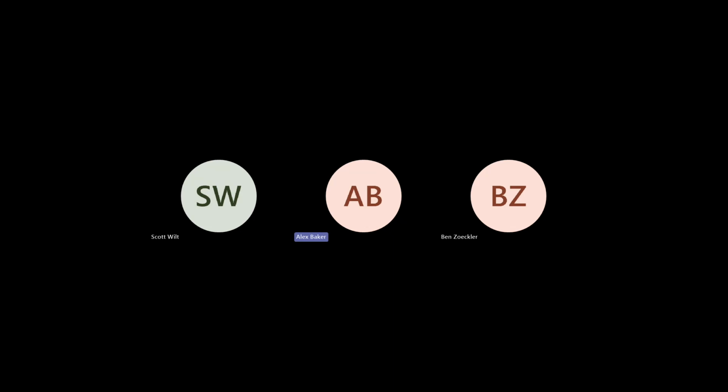Yep, that's fine. How do you create a time series animation? Up in your animation toolbar, where you press the play button for the melt front animation, there's a little video drop down. There should be a melt front style of output, and then there's also a time series style of output. So if you're looking at the cooling temperature result, you can create a time series animation output of that result over time.